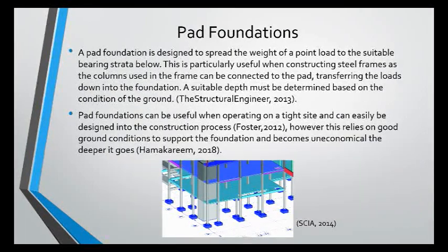Pad foundations transfer the point loads to suitable strata below, useful when constructing a steel frame structure, but will require good ground conditions. This is good when operating on a tight site, but can be more costly the deeper it is required to go.